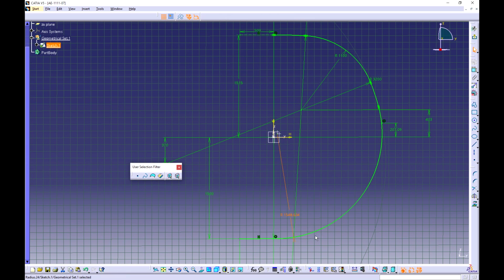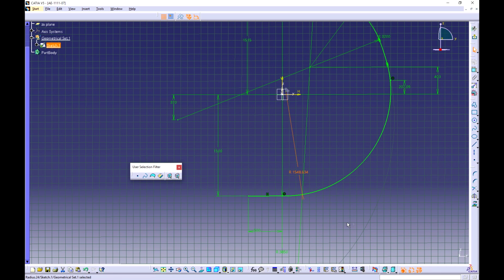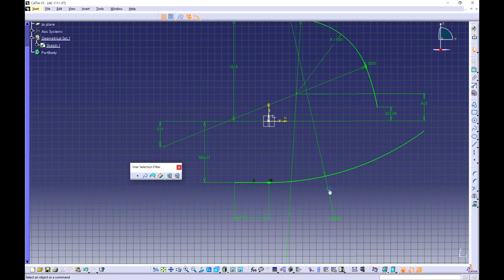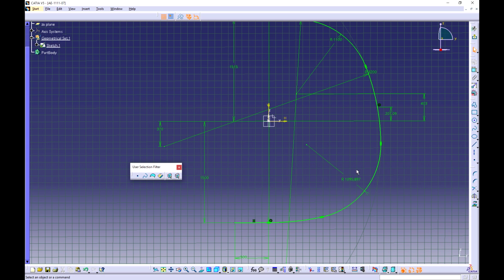Now we have like two arcs. Unfortunately, it doesn't look that good in mine. So I just go back and make it again. So again, the corner tool. Select the first one, the last arc. Like this. Now we'll change the parameters again for the first point of our straight line. The distance between the x-axis and our first point to 1500. And now it looks better.